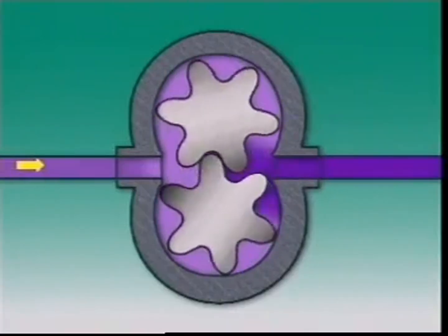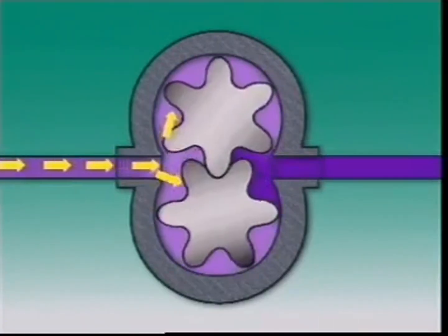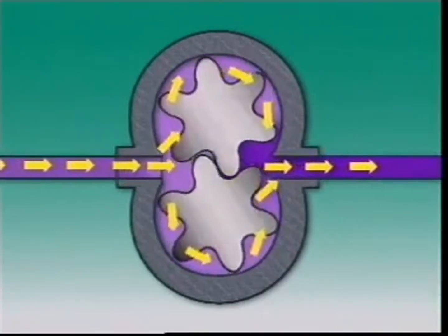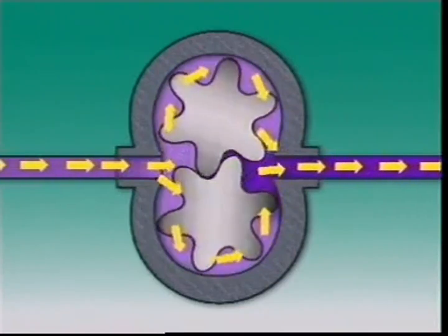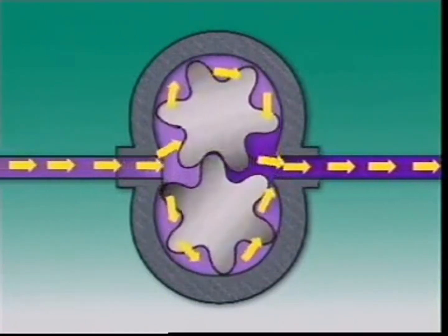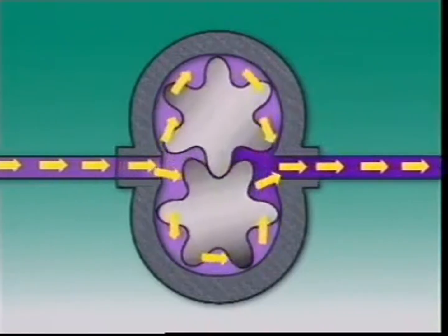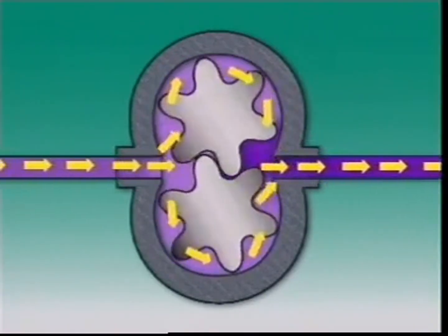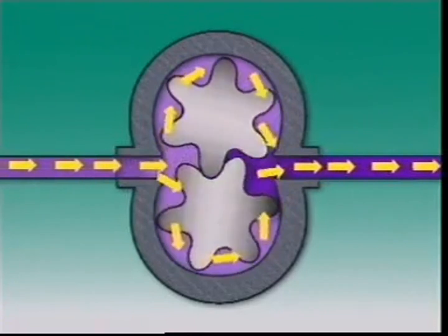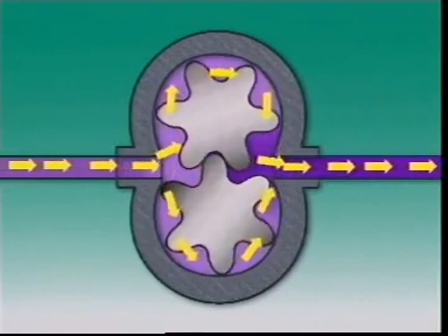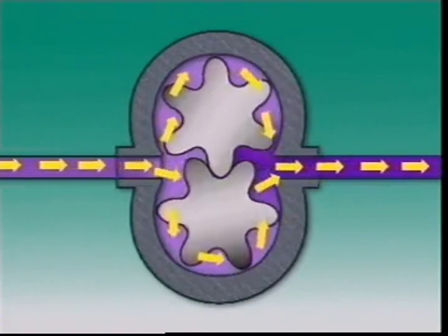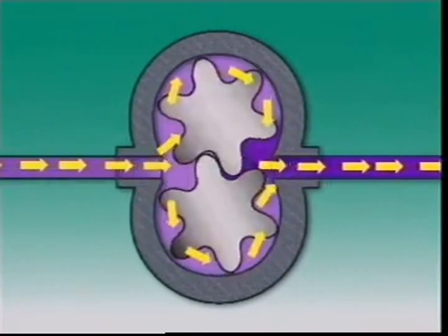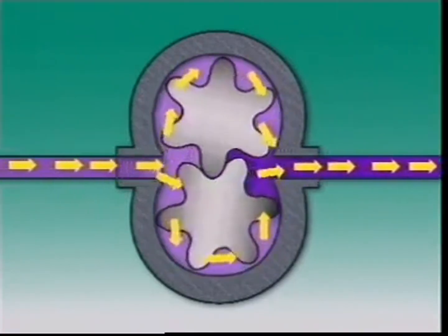Similarly, in a geared oil pump, the driving gear meshes with a second gear. As both gears turn, their teeth separate, creating a low-pressure area. Higher atmospheric pressure outside forces oil up into the inlet. The spaces between the teeth fill with oil. The gears rotate and carry oil around the chamber. The teeth mesh again, and oil is forced from the outlet toward the oil filter.